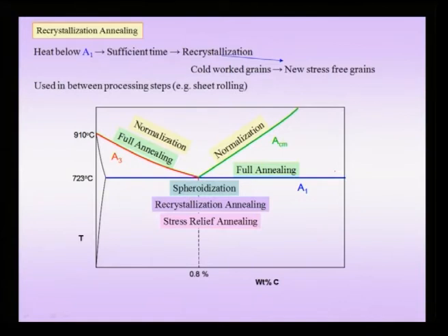Recrystallization annealing, and we will try to understand this term recrystallization in detail later on, and we will see it is not just a phase transformation, it is a term related to microstructure transformation, and typically you would like to carry out recrystallization to restore ductility in a material.